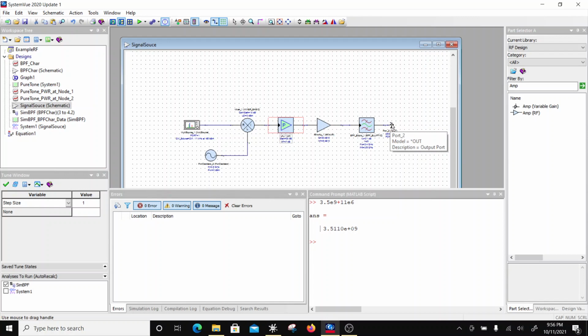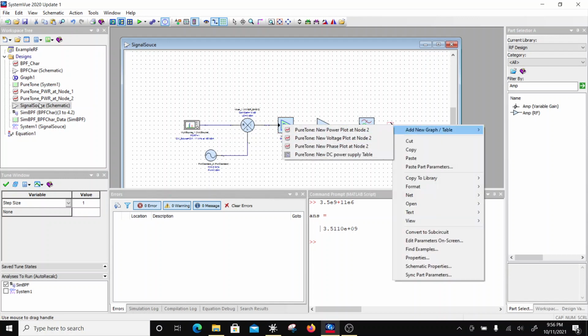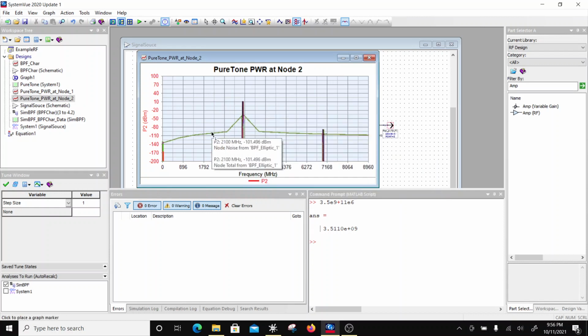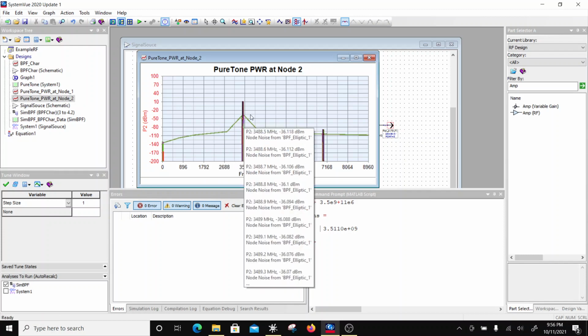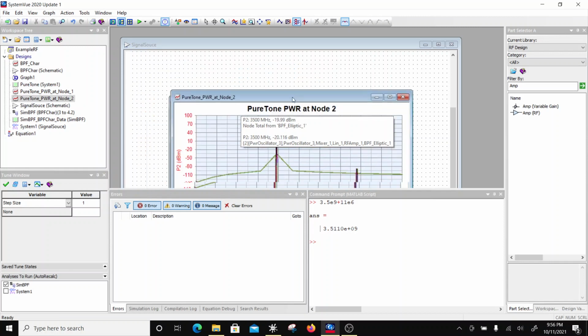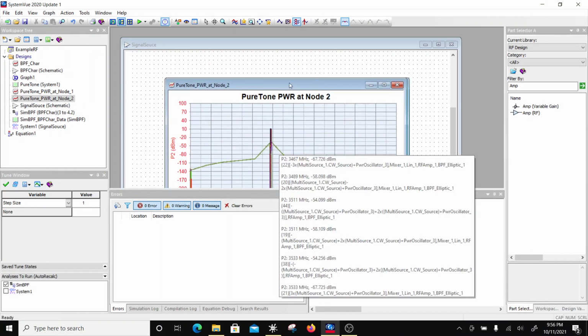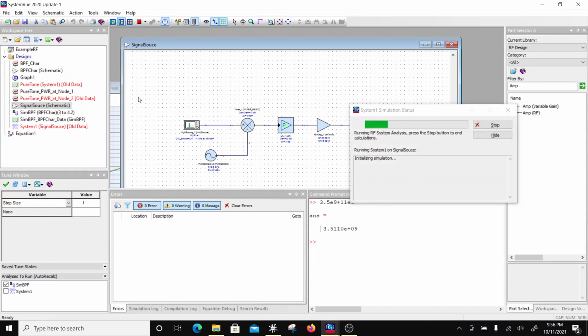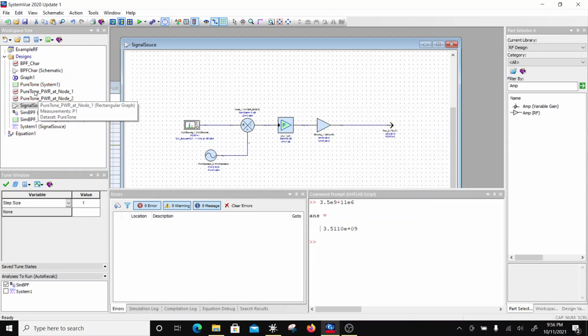And what you have looked at in this graph is that, and this is the noise contribution you can see in this graph. Okay, so this is the noise, and earlier before the filtering you see that the noise level was up everywhere unless you do the filtering. So for example, if this component was not there, right, and then you looked at the analysis. So the function of the image reject filter is to filter the noise which will fold over in our band of interest, and we want to avoid that.